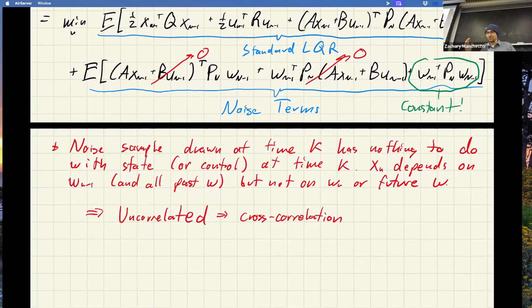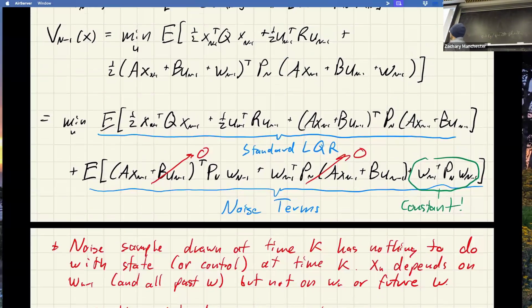from this, that I will now explicitly spell out to you. So what this told us is that the noise terms in this whole thing, all the stuff that coupled, dropped out. The only thing left is this constant term that just depends on the noise covariance, the cost over plain LQR stuff. So if you think about this for a second, the repercussion here is that the noise terms, all the stochastic stuff, has literally no impact on the controller design or the feedback policy that you should use. All it does is add a higher cost.